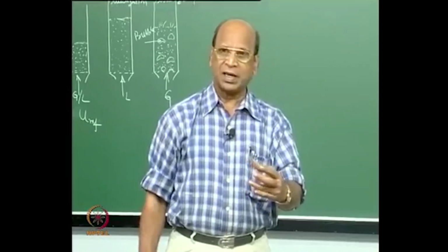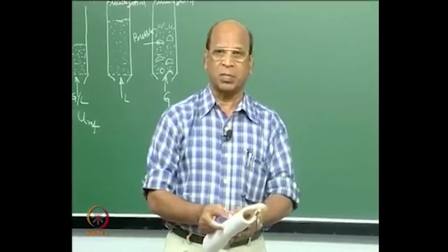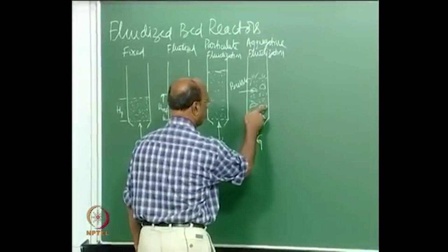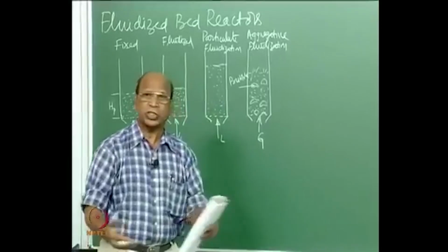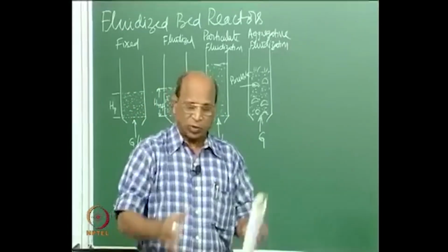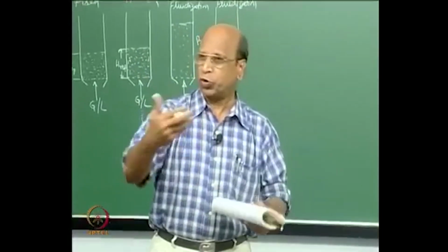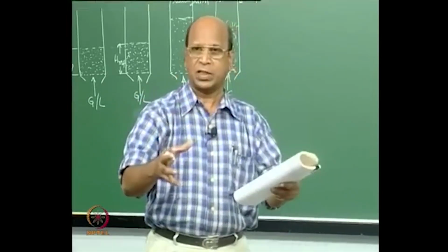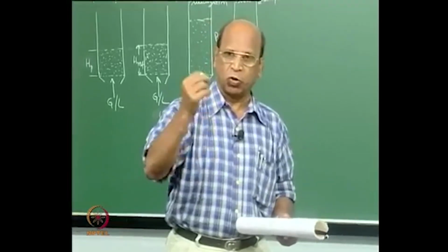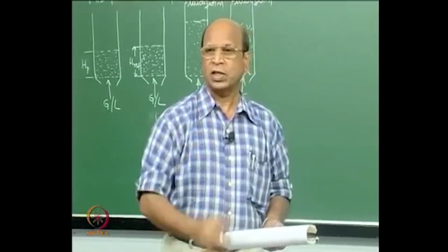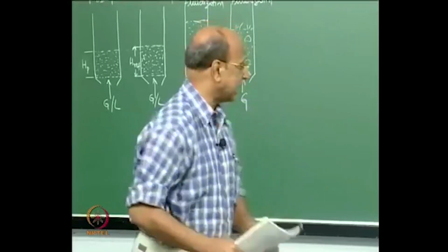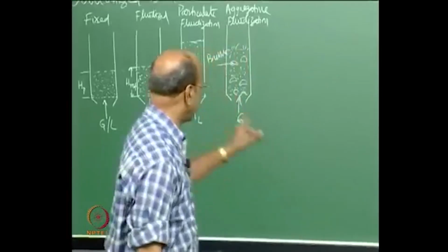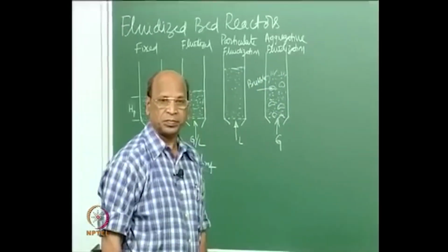So, that kind of sophisticated methods are now coming to measure, okay. When you have a 3-dimensional column, you will have some bubbles here, on the back side also, this side also, and this side also. Which side do you measure? Whatever side you focus on is not uniformly reproduced all the time, so they take measurements from various sides and then average the bubble size. Bubble size is one of the most difficult parameters which we have to estimate properly, and that itself is the starting point for all our calculations. That is the reason why gas solid fluidization is very difficult.